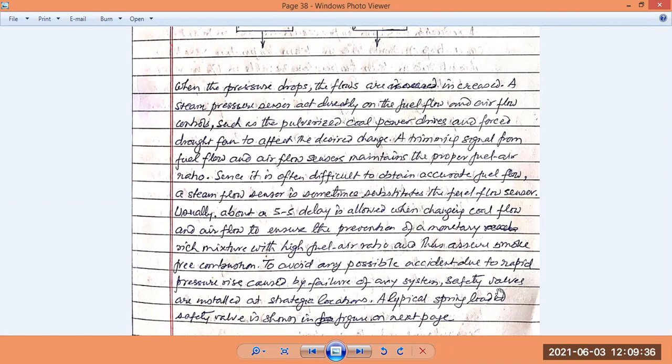How is the air coming? Through a fan. It can run faster, slower, or at medium speed. Pulverized coal, you are supplying it. Coal should not be the same size as when you took it from the mine. You have to break it down by pulverization, to a certain size, and it is supplied through a conveyor itself. And you can control both of them, the airflow as well as the pulverized coal flow.